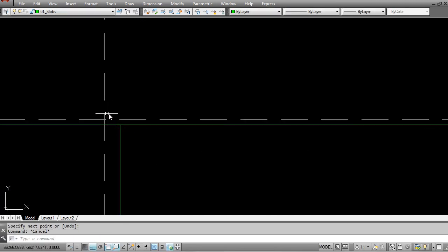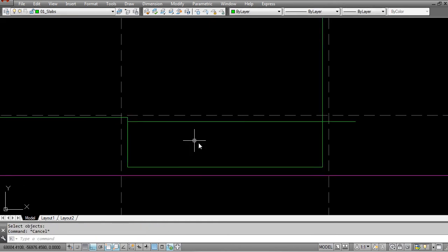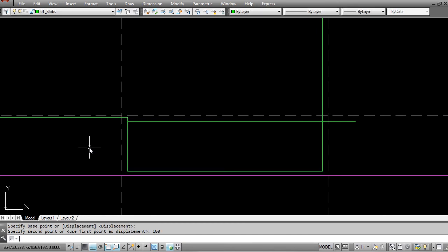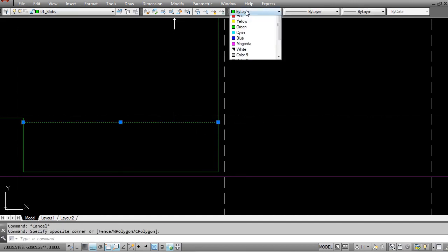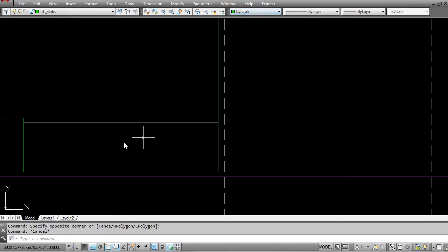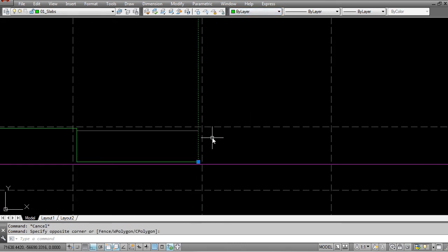And here we have that rim flow edge, and since the water level is not going to be overflowing over this, we want to offset that by about, let's say, 100 millimeters. We can also stretch this downwards by that same 100 millimeters so that we retain our 1.2 meters of water depth, and this will now represent our water, this line over here. That won't be green anymore, that will be a much lighter color, and we can later hatch that in or do that in the Photoshop phase of this course.